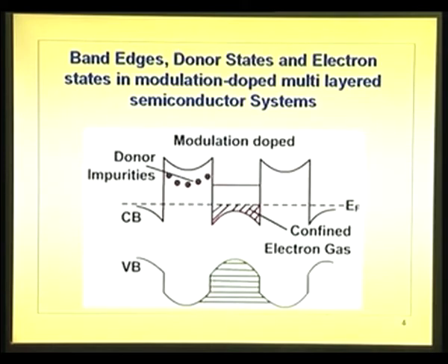This is just, I have showed undoped, all the layers uniformly doped n type, and the next one alternate layers doped, that is selectively doping this portion. These will be layers arranged one over the other. On the top of the bottommost layer will be that, you can go on to the top. So, the energy band diagram is drawn horizontally, but layers are one over the other. So, you grow layer after layer, one layer you dope, next layer change over to aluminum gallium arsenide, dope it. First layer you do not dope with gallium arsenide, dope this layer, do not dope it, dope it.